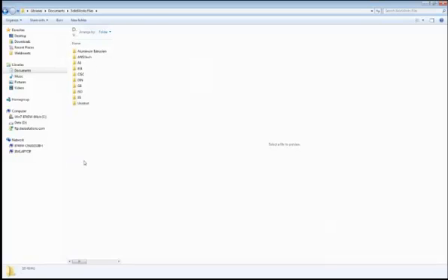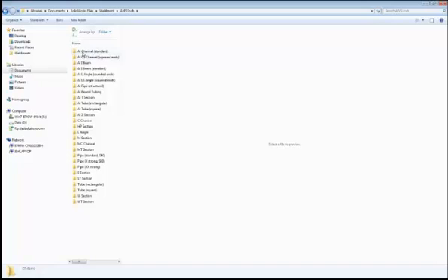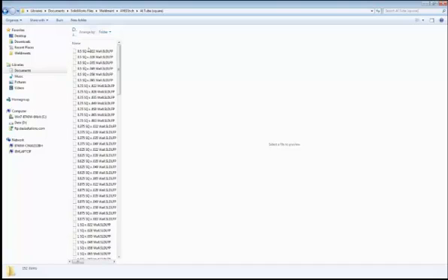I have a folder for Weldment profiles, and these are all the standards that you can download for SolidWorks. And you'll notice that under each of those is the type of profile. And then every profile that you use is a separate file. It's a library feature file.